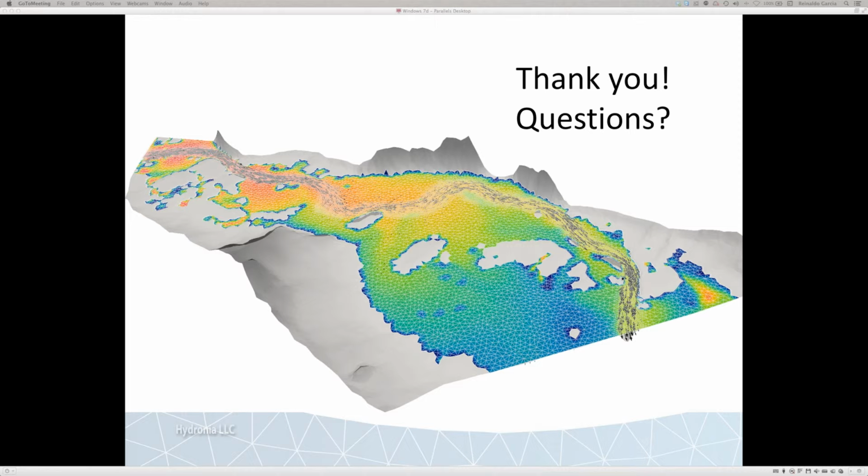You can do that with the rating table now, because the rating table can be set up so that when you reach a certain water elevation in the river, you can put a zero discharge through a part of the structure. But the calculations that are done now do not account for that. It would be an interesting thing to add in the future.